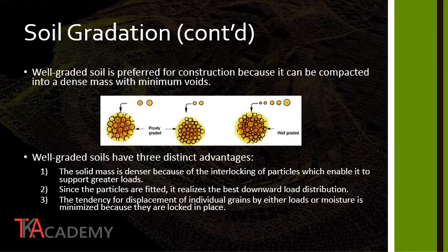The reason that we use the term well-graded is because it is typically preferred in a construction project to have soils that are diverse in their particle size, because they can be more compacted into a dense mass with minimum voids and become a much more stable base.